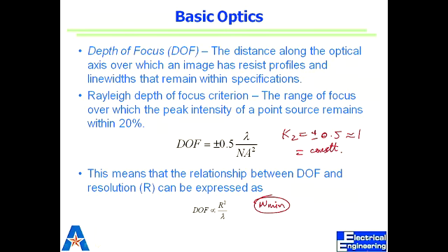So if you are given a problem where you have features at different heights and you know the maximum height of a feature on a substrate, that is your minimum depth of focus, the depth over which you want to register your pattern on that wafer. Does it make sense? If you know the height of the tallest feature on your wafer, you have to have a depth of focus larger than that. So we do run into this problem where the numerical aperture that we work so hard to increase is too large, and you will be compromising your depth of focus. I see.